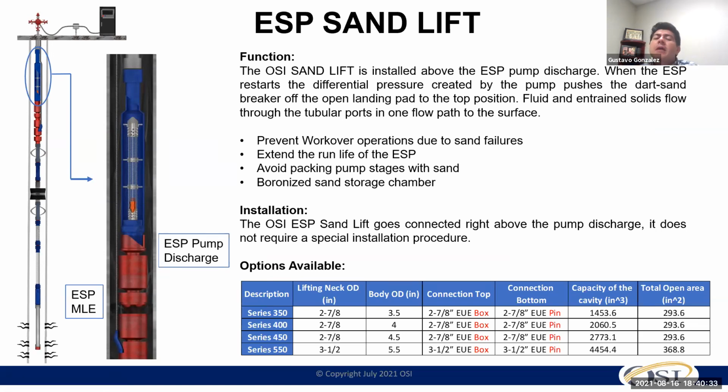There are different approaches that people have used in the past. Either they put a check valve just above the discharge to control the sand that is falling back, and they want to have that head kind of free. So when I restart my pump, I'm able to use that pressure to open the check valve and flush the sand out again to the surface.